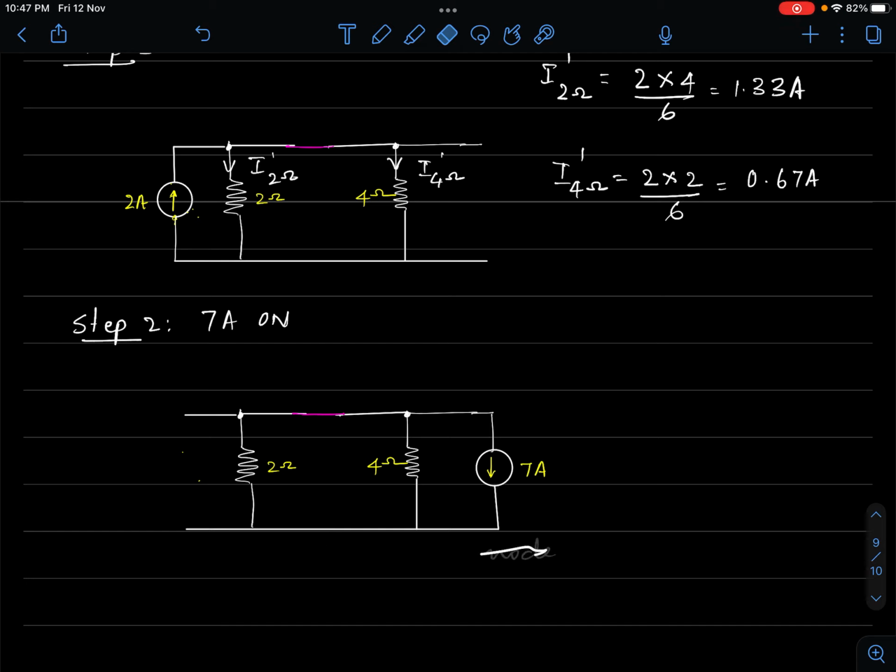Okay. So now how is the current distribution? The current distribution has to be given a different name now. The direction of flow of current is now this way. Because we have only one current source, we can actually find out the current direction. If there were multiple sources, then we may have to assume an arbitrary current and then evaluate. If we get the positive sign, then we infer that the current assumed is correct. If it is of negative sign, then we conclude that the assumed direction of flow of current was incorrect. It is opposite to what exactly is flowing.